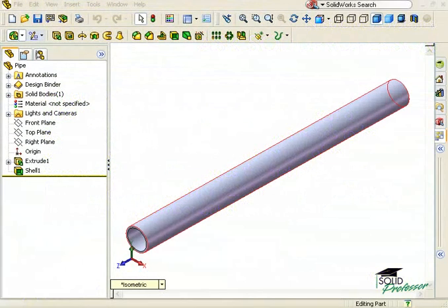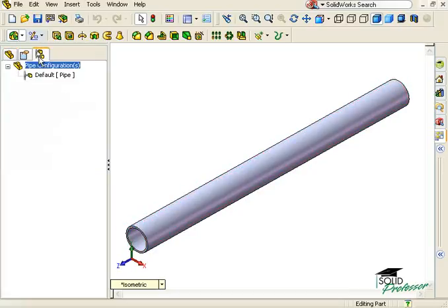In order to have multiple instances of a part model in an assembly, where each instance can vary in size, you must use configurations. Configurations allow you to vary the definition of a part or assembly, including dimensions, features, and material properties. To create a configuration, enable the Configuration Manager using the tab at the top of the Feature Manager tree. Every part will have a single configuration called Default.